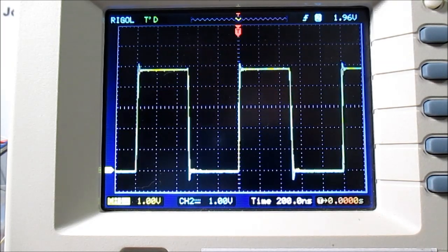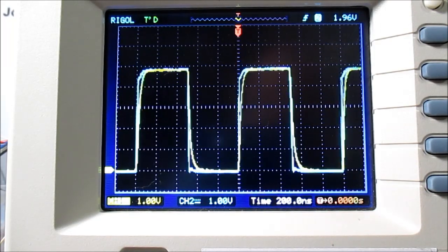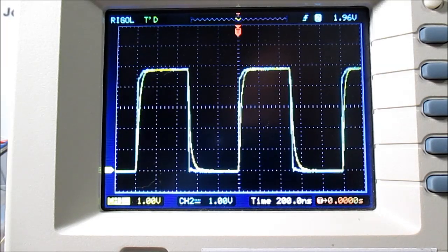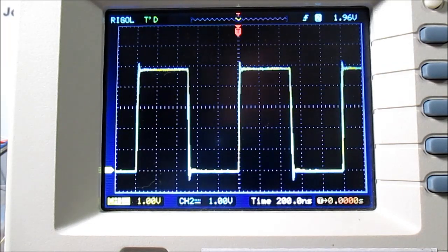Now I'll show you another interesting aspect of the diodes here. I'm going to connect them in reverse bias. So they're not actually going to turn on, but you still will see an effect. See what's happening there? That is caused by capacitance. This is the 1N5404 again, and there is some capacitance. Whenever you have a differential in voltage at a very close distance, you're going to have capacitance effects across that. So that was the 1N5404.